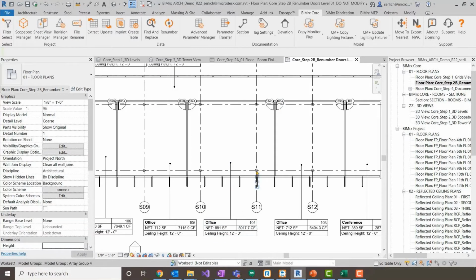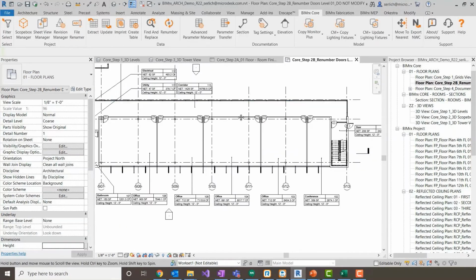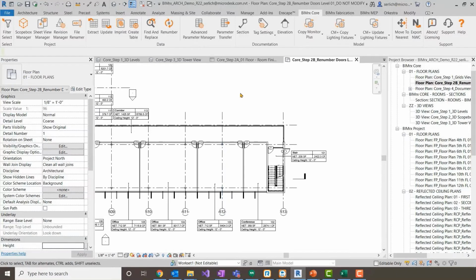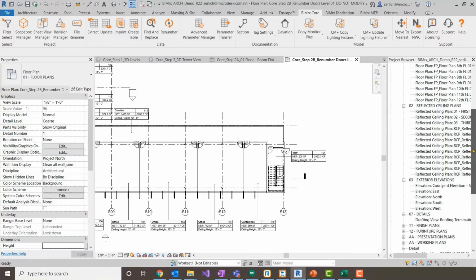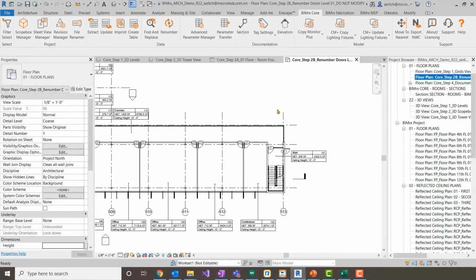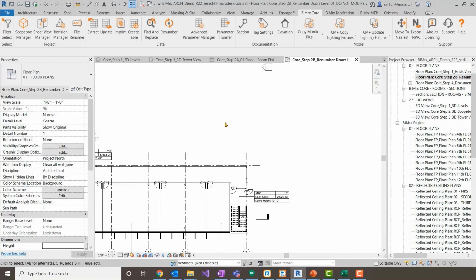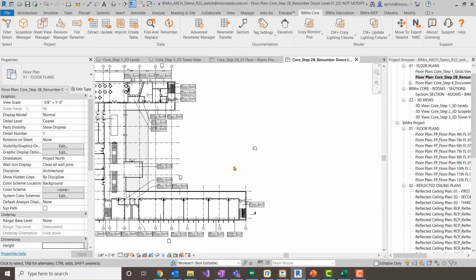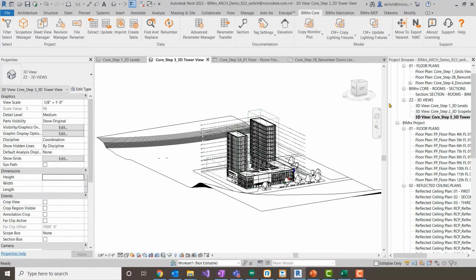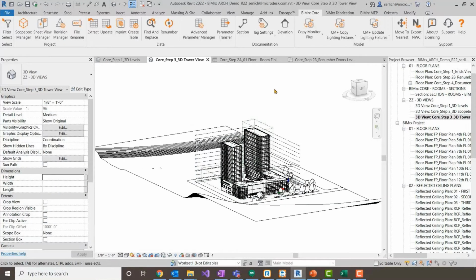And now that we've finished managing all of that data within the Revit model, let's take a look at how we can use BIMrx to create our documentation set. I mean, we just went through project setup, right? And then we went through that model management, and now we need that final step, that documentation. And before we can actually start documenting our drawings, we need to create all of our sheets and place all of our drawings on their respective sheets. That's where the BIMrx Sheet View Manager comes back into play.